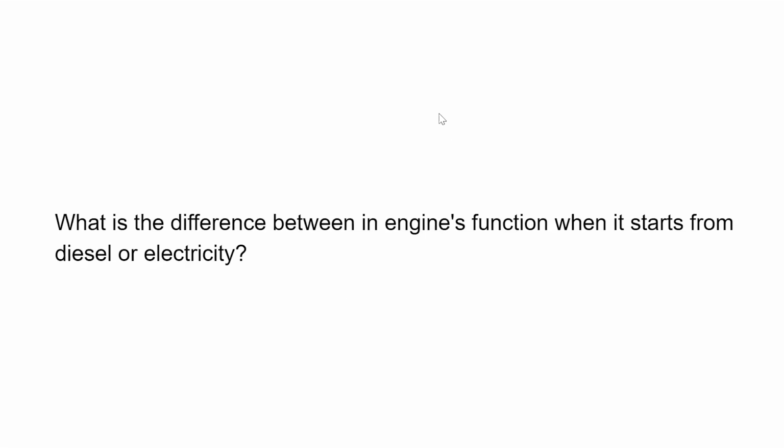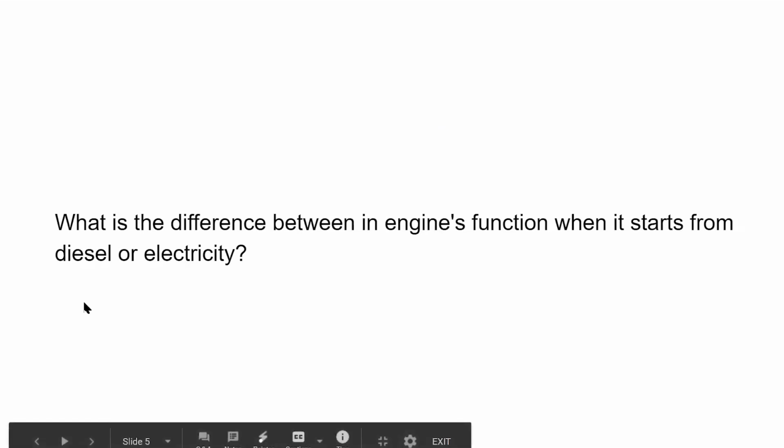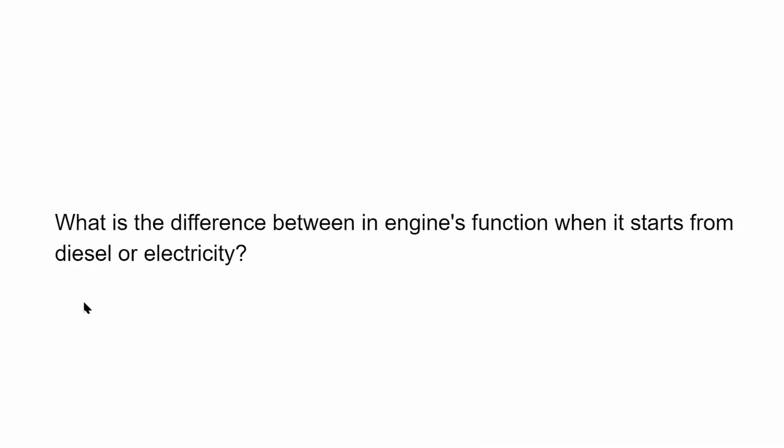The electric motor, in many cases, is directly inside the wheel, so it's called an in-wheel motor. And the engine, as you all know, is in front of the car most of the time. The difference in the characteristics is that the engine has high efficiency at higher load. So when you're driving on highways at faster speeds, that's when your engine has the maximum efficiency.